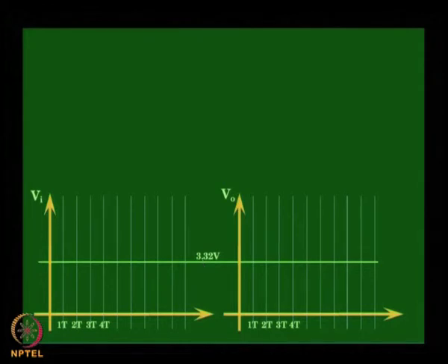the source impedance of 25 ohms, and if there were no transmission line effects, it would have been 300 divided by 300 plus 25, 300 by 325, which will give you a voltage value of 3.32, which should immediately settle to this value. Now, let us see what happens due to transmission line effects or the reflection problem.